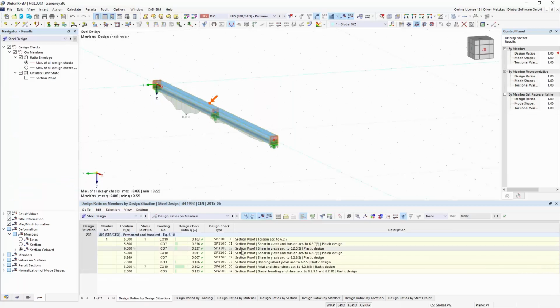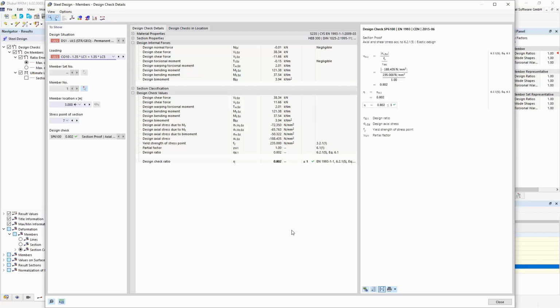And then I will see all the steel design checks with consideration of all the internal forces, including beam moment, secondary and primary torsion. If you look briefly in one of the design checks, for example the most governing one here, then we see in the results we are calculating the equivalent stress, considering the stress from bending moment about strong axis, weak axis, and also the axial stress from the warping beam moment. So all the necessary internal forces are included, and then we also use this gamma M1 factor for our cross-section design check, because it's meant as replacement for the stability design.